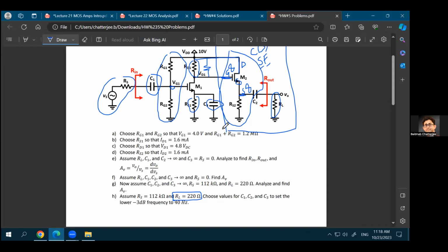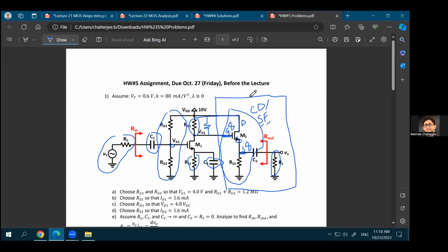And that's what you want, that you want very high gain out of this stage, and then the second stage will just work as a buffer. It will try to drive any amount of load that you put at the output side, but with a gain equal to 1. So that's the purpose of this second stage. And the buffer or driver is something that you'll see again and again in this course, and also if you take any other advanced course in circuit design.